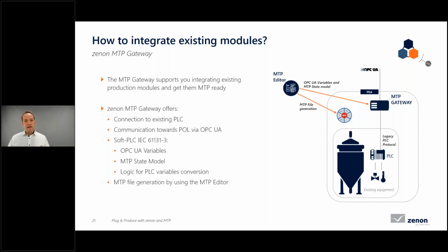And with the MTP editor, you create your template file, and at the same time, it is creating logic code to be run on such a device. This gives you the possibility to have the MTP state model included, connecting your legacy protocols, your legacy tags, and also prepare the device to be connected to the process orchestration layer via the OPC UA protocol. So it's a really nice, easy way to integrate existing equipment.